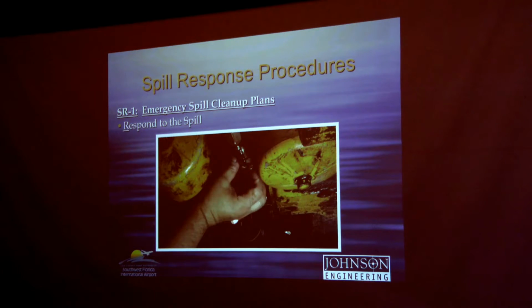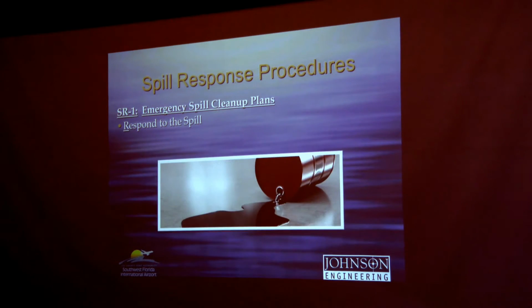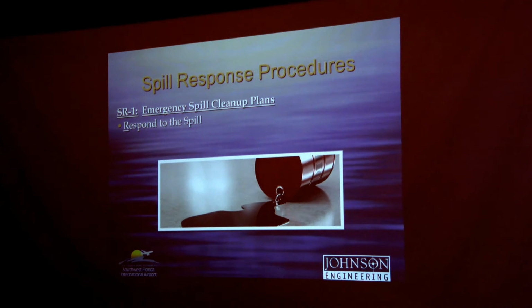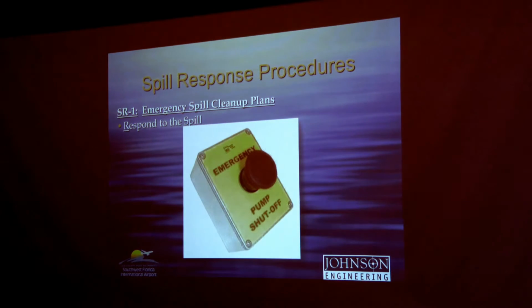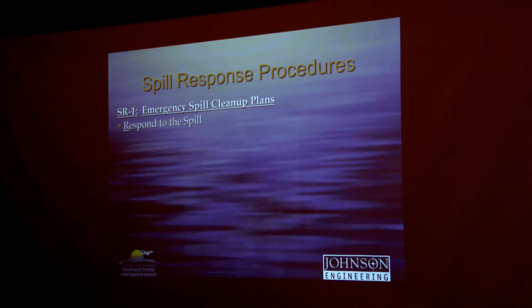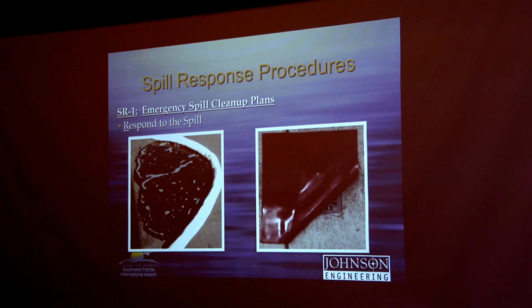Stopping the spill can range from fixing small hydraulic leaks at vehicle maintenance, righting an overturned drum, or closing an appropriate valve, or hitting the emergency shutoff button. Once the spill is stopped, evaluate the spill to see what direction it is traveling. Your next priority needs to be to stop the spill from reaching a storm drain, ditches, or unpaved areas. Drain covers and booms can be used to protect these sensitive areas or to direct the flow of the chemical into a more manageable direction.